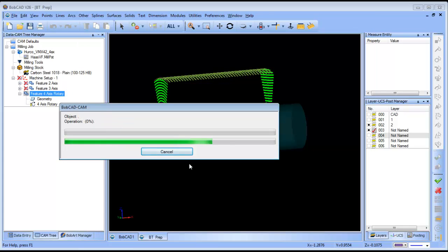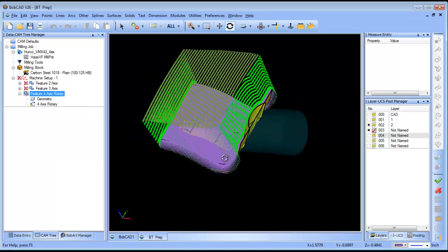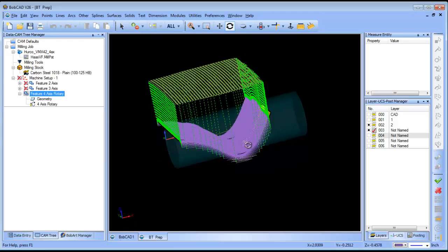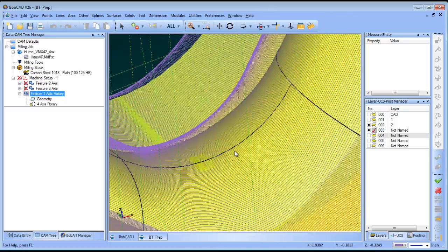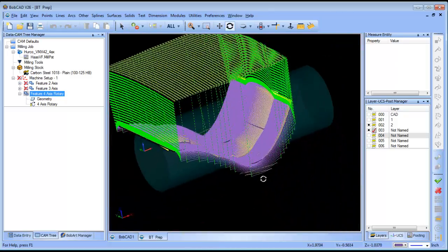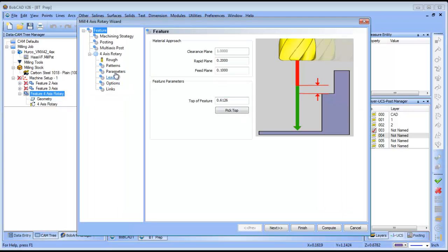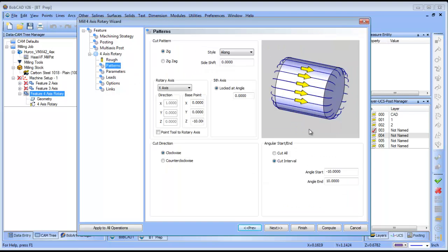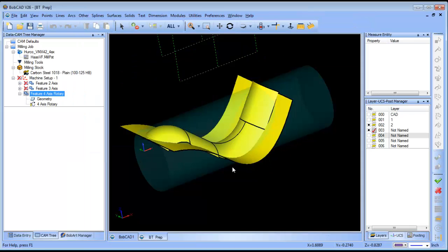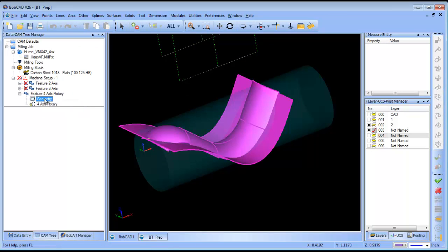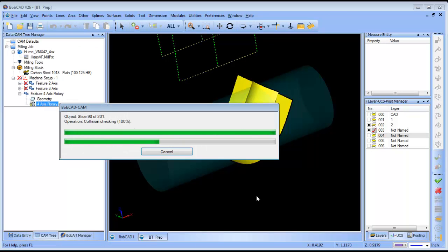And now we should see a pretty decent toolpath strategy to come along and cut the surface, and it actually looks pretty good. The only thing that I want to do is shorten my angle range so that it's not going over the edges there. So we'll edit the angle range down to let's say -5 and 5. Let me reselect. Recompute.